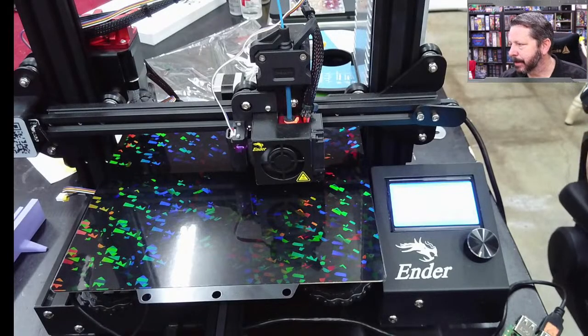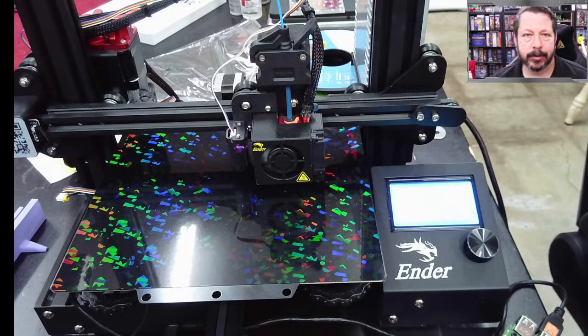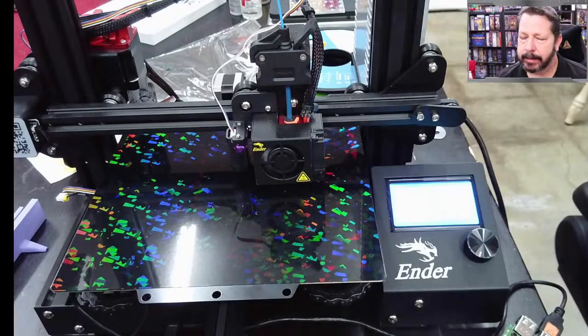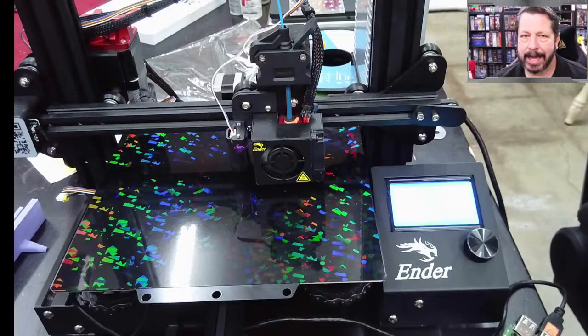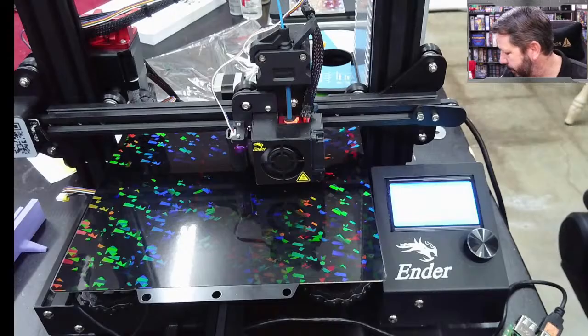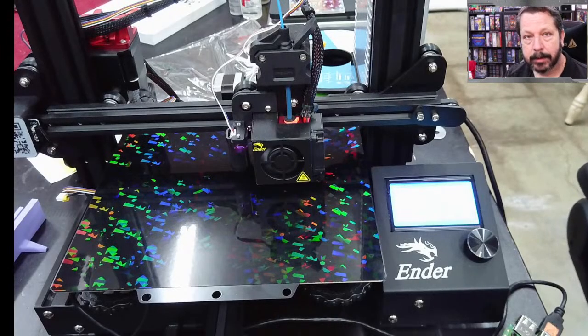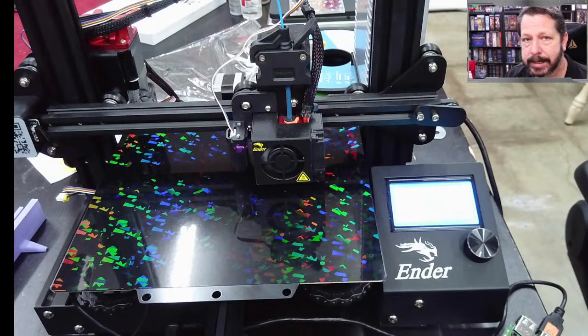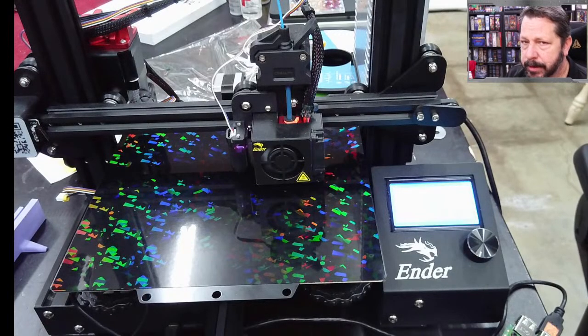So you might have to go in and create your own temperature tower if you wanted to print with a raft. But a raft, I mean, the temperature tower is not this kind of small part I'm thinking of. I'm thinking of small parts like tiny little individual pieces, but that has a big enough base that you shouldn't need a raft for it.